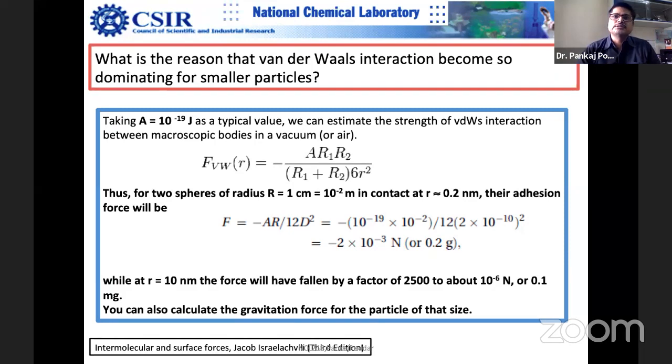When this roughness is less than the wavelength of the light, then you can say that it is optically smooth. You can do a very simple experiment to check whether it is; you don't need any hi-fi instrument to check whether the surface is optically smooth or optically rough. Just take any ruby red laser, like those available in laser pointers, and shine that laser at the surface.